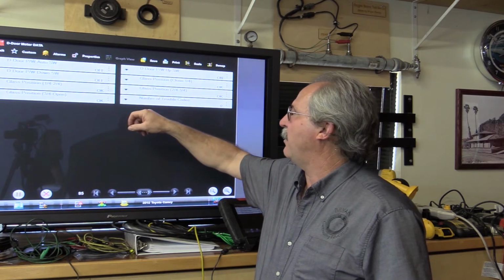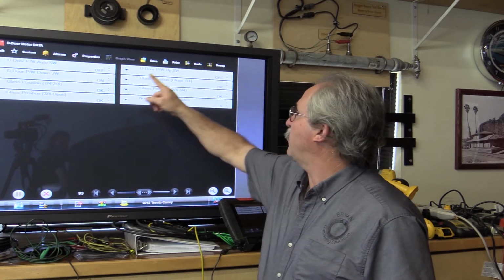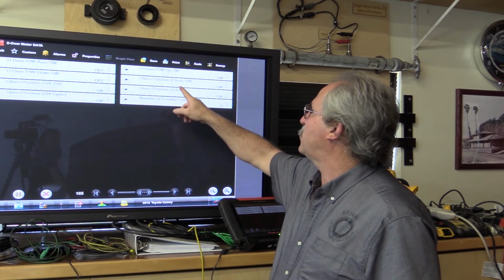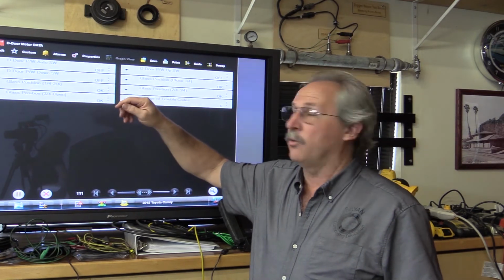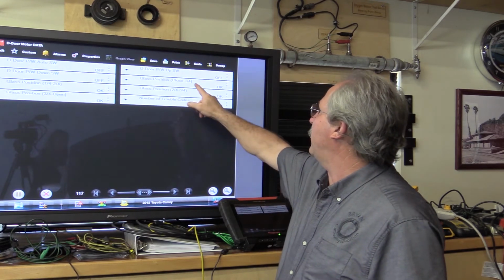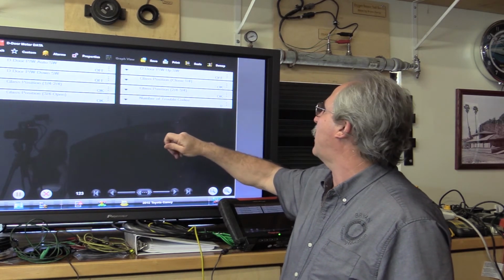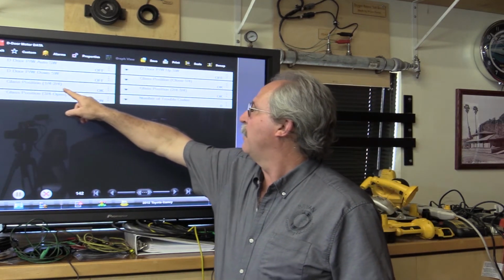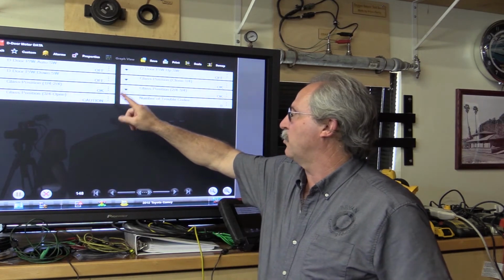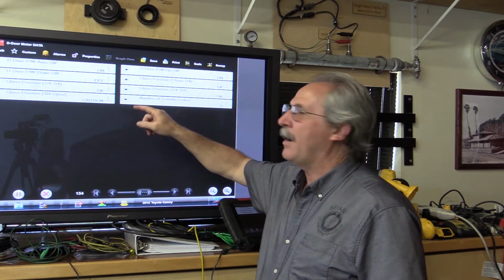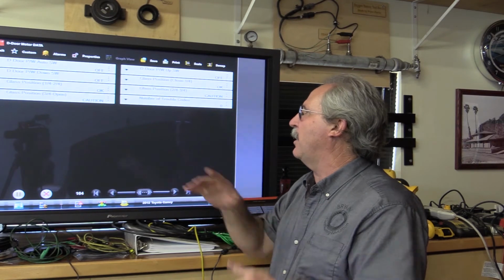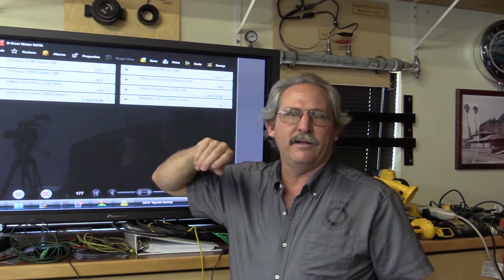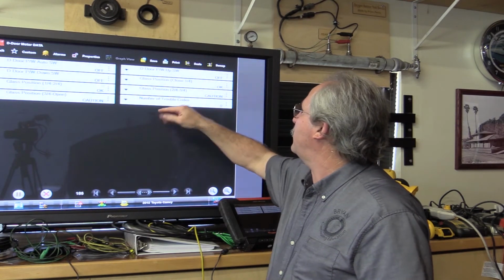So the power switch is down. And we can see the up switch and the down switch go. If you go up a little bit further, and then stop it while it's going up with your arm, you'll see that it gets too much tension, it'll go to not okay and stop the window. There you go. So I just got a caution here between 1/4 and 2/4, or between 1/4 and 1/2 on the way up. So if I have a window that's sticking or not working, I can see not only is it binding, but where the problem is at. So it allows me to see this, and the window will stop working.